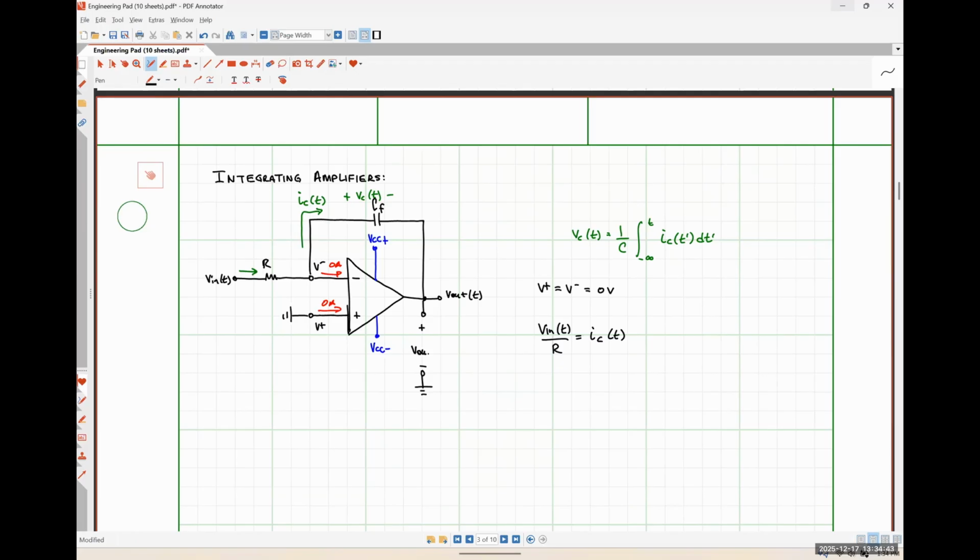So our output voltage, V out, is a nodal voltage, meaning that it is measured with respect to ground. So I've explicitly drawn that down there, okay? The reason why I've drawn it that way is so that we can see that the positive polarity terminal of our capacitor voltage is at a node that has a voltage of 0. And the negative polarity terminal of our output voltage is at ground, okay? The negative polarity terminal of our capacitor voltage is at the output node, and the positive polarity terminal of our output voltage is at the output node as well. So essentially, V out and VC are the same voltage, just of opposite polarity. So I can write that V out is just negative VC, okay?